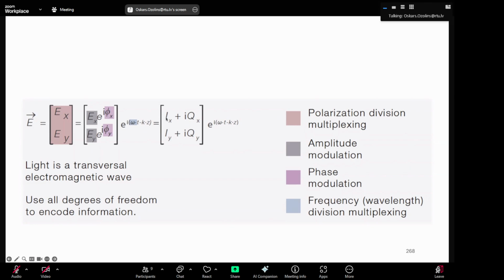So for example, in case of QPSK, I and Q both contain non-return to zero information, so 2 symbols in each, and then plus polarization. So that gives another way how to scale how much information we can transmit within the same bandwidth.